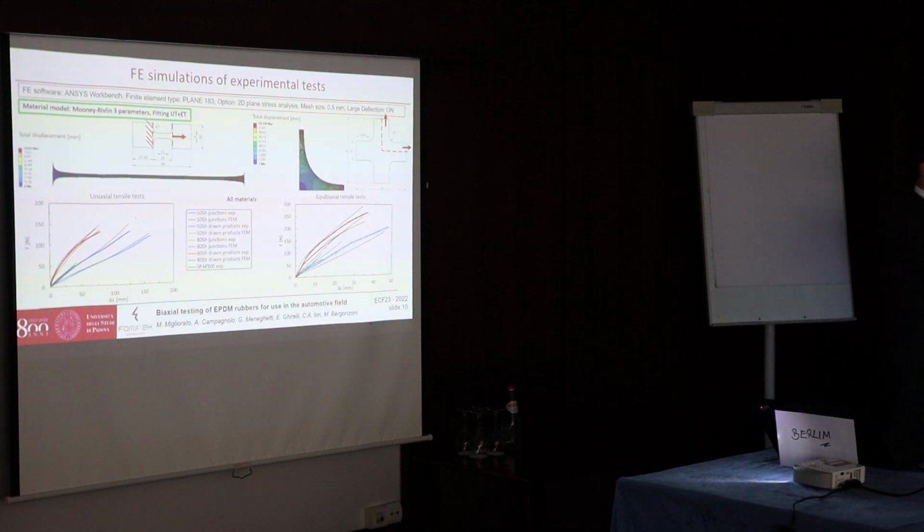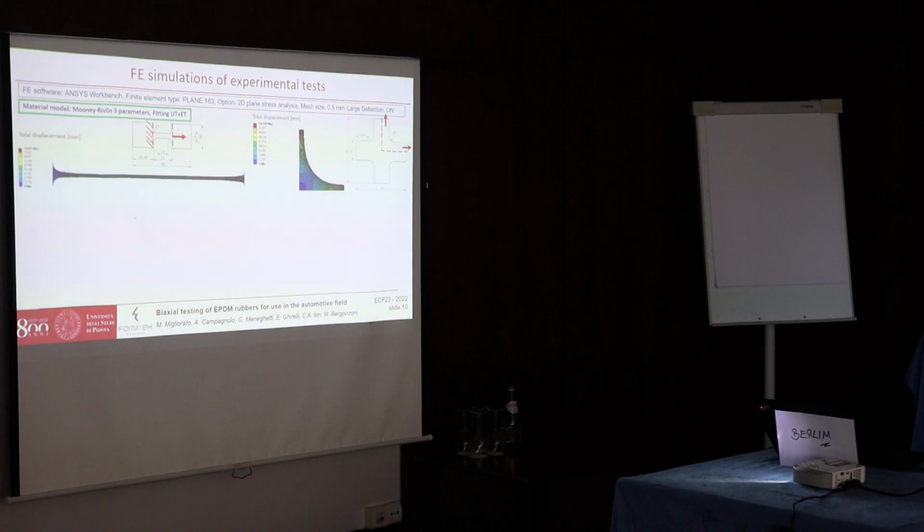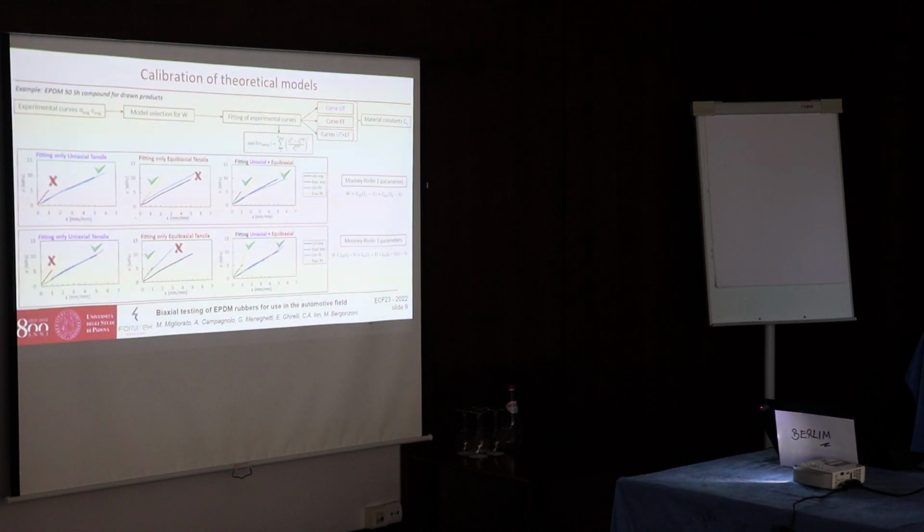Thank you very much for your talk. I was wondering, on the modeling part, which other models you considered for your strain energy function. The models that we have adopted? Yeah, because the Mooney-Rivlin model is a phenomenological model. I wonder if you considered microstructurally based models, which account for chain orientations and this sort of thing.